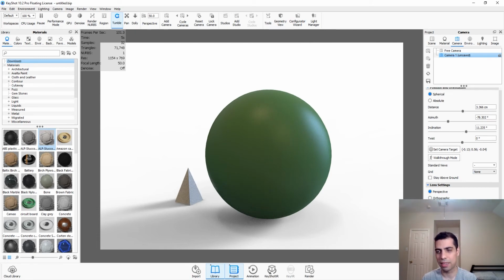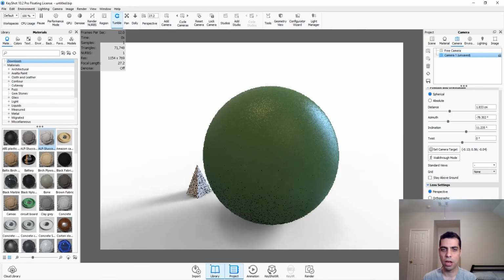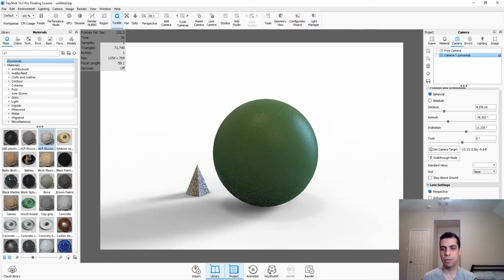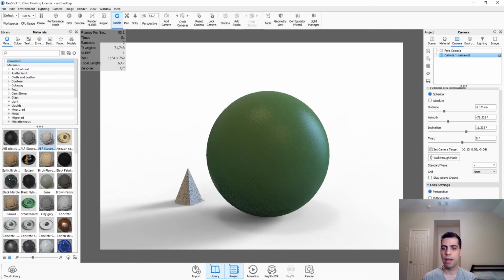Perspective is obviously perspective. You can change the perspective value or the focal length, and you see how it's changing. The higher you go, the more orthographic it would look. Based on another tutorial and on experience, I know the best value for the focal length is between 65 or 67 to 70 millimeters. And field of view, obviously, just goes back and forth.